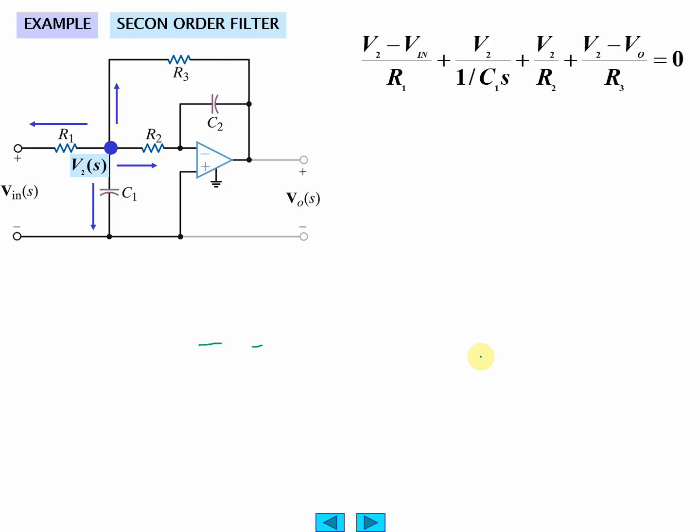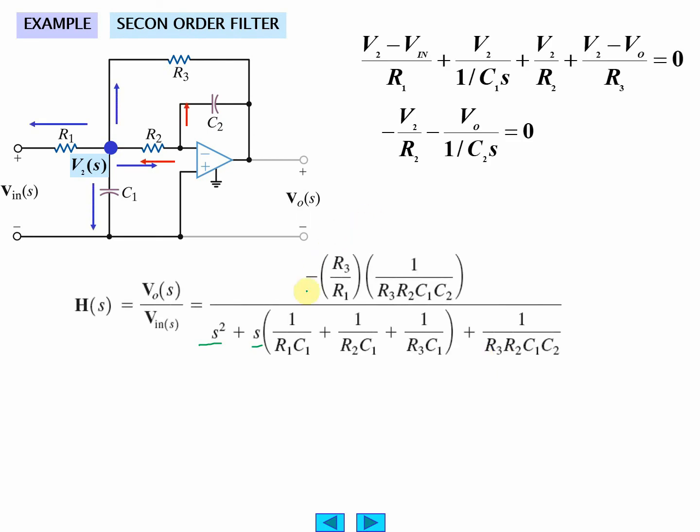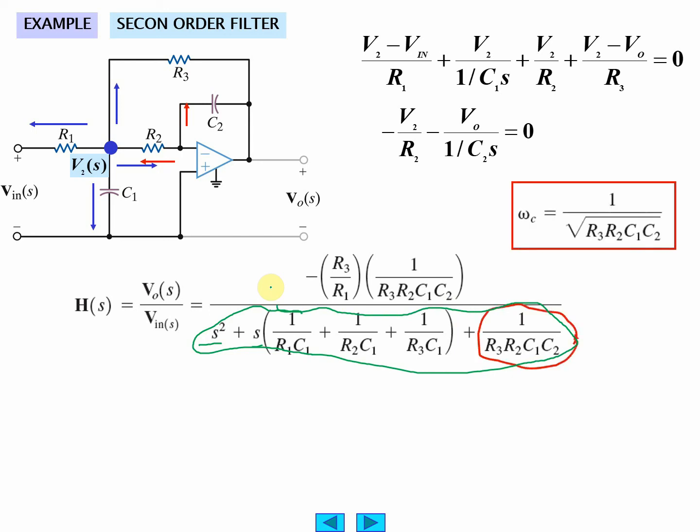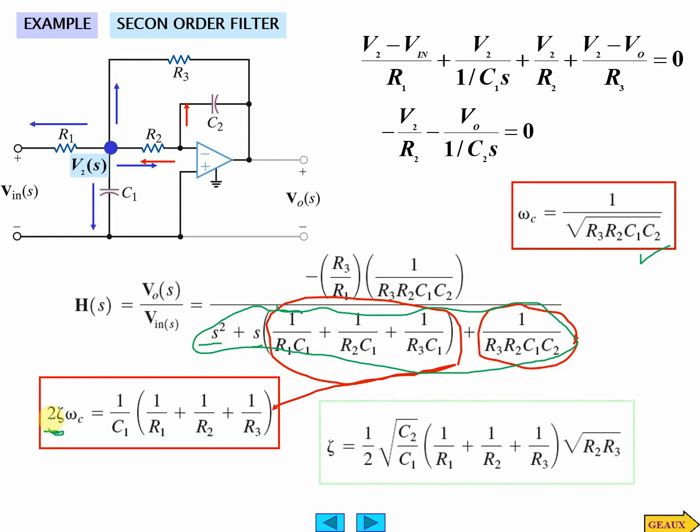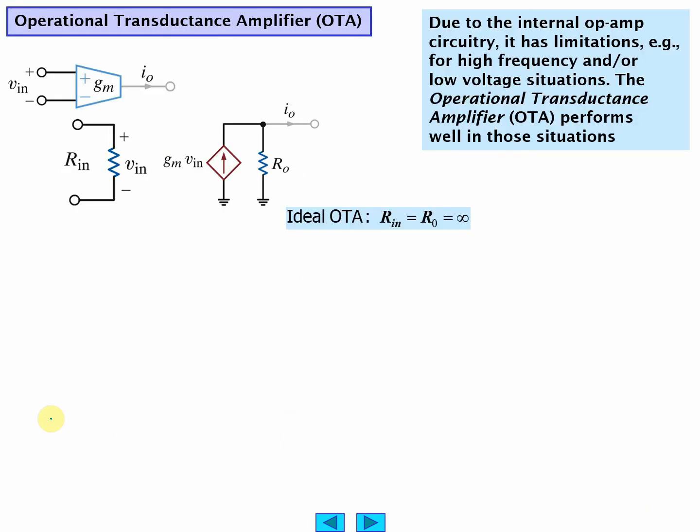Now this one here acts like an LRC, but now you don't have any L's floating around, and you can tune it. So here's your omega term. Okay, this is your quality term, 2 zeta. So we're just going through designs. We're not going through all the math. Let's see. This looks like a good place to stop.